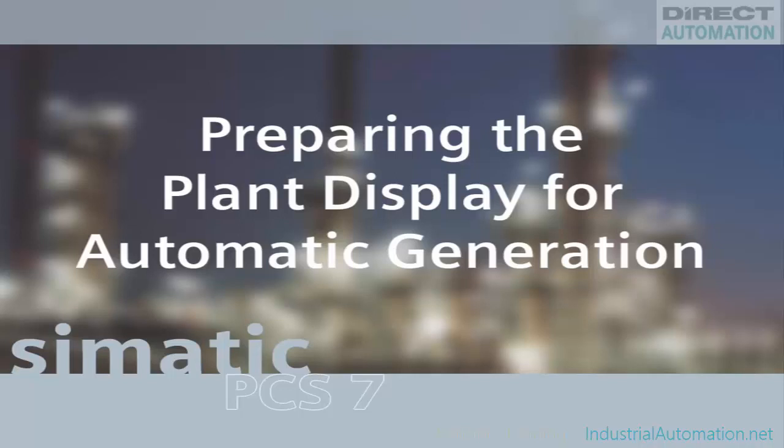In this sequence, we're going to show you how SIMATIC PCS 7 automatically populates process graphics with symbols which are pre-linked to function blocks in the controller configuration. Based on the controller configuration, PCS7 can automatically create symbols which allow the operator to control and monitor CFC and SFC charts from process pictures. These block symbols are automatically linked to their associated faceplates. Generation of these block symbols and the process for linking a symbol to a faceplate can be executed on demand.